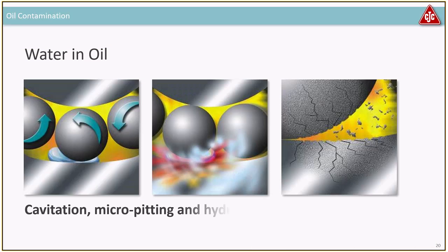So we didn't like particles in oil because they destroyed our pumps, our valves, our everything. What about water? Yeah, water is also destroying my components because of different things. Well, water can do something called micropitting. That is, you see here a roller bearing. There's extremely high pressure in such a roller bearing, and the oil can actually solidify under this very high pressure, but water cannot.